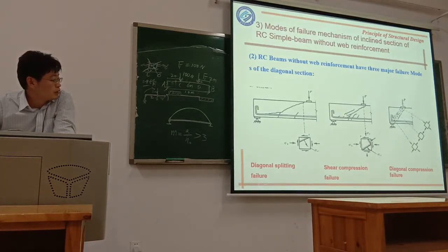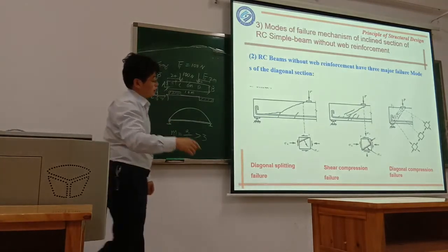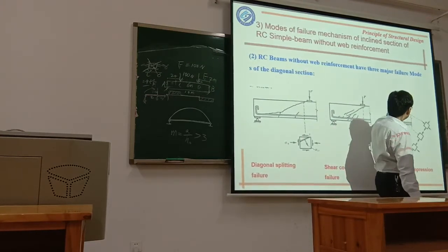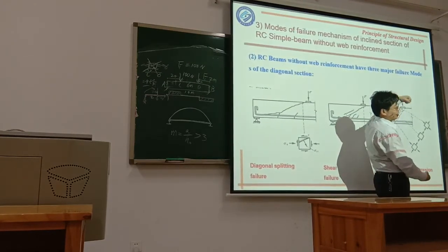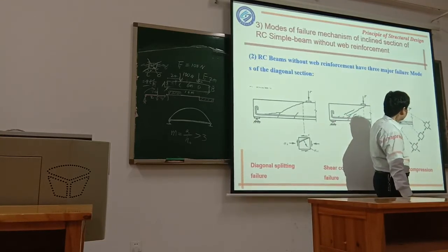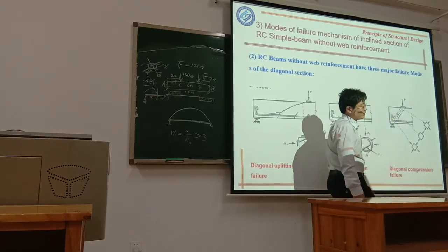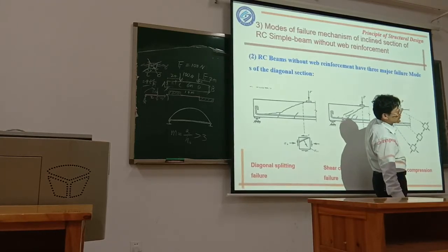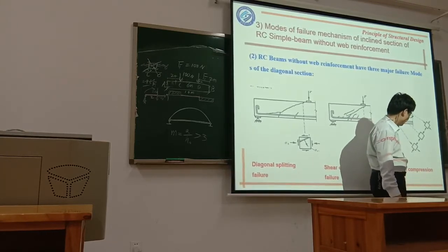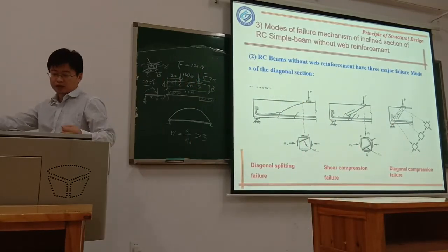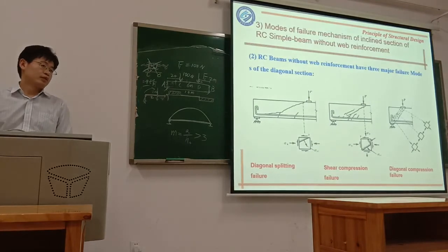When the action point is near the supporting point, you can just imagine the limit state, the force moves toward this point, just in compression. So when m is smaller than 1, that means this distance is smaller than h0, this part is mainly induced by compression failure. The concrete is the compressed part.